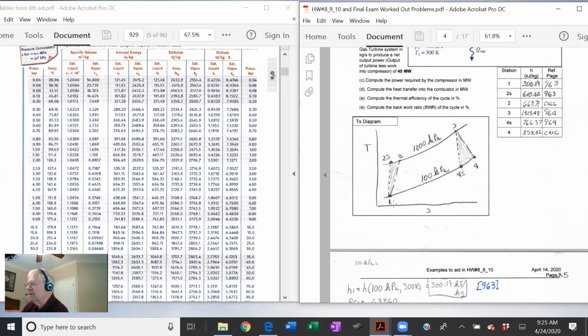But I want to see, all right, we're coming in at state 1, atmospheric. We go isentropic, our ideal reversible process, the 2S, straight up. The actual process increases entropy, it goes to 2. So that's a compression process, from the low pressure to the high pressure. Then it goes through the combustor. We don't really show that. That is process 2 to 3, constant pressure. Temperature goes way up due to the gas being ignited. So we go to state 3, coming into the turbine.